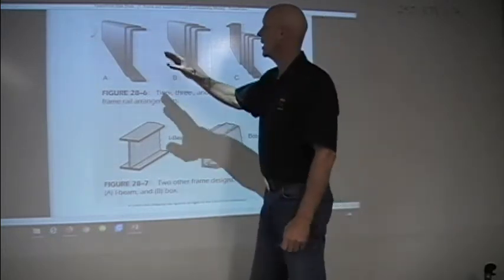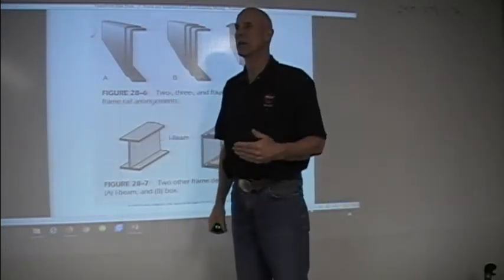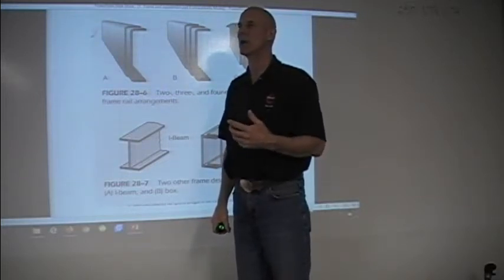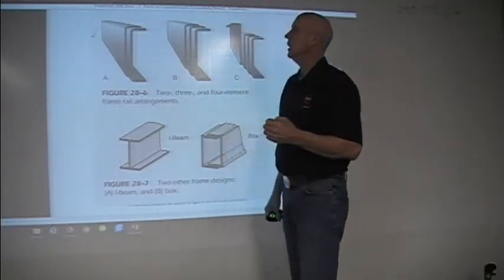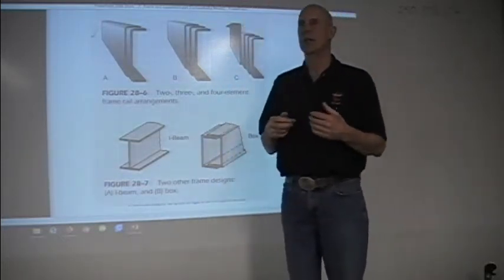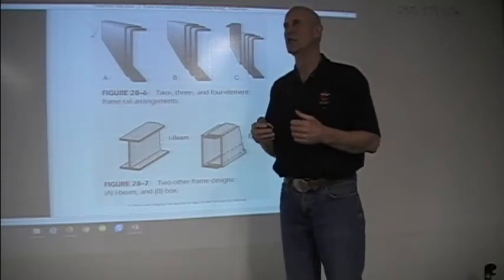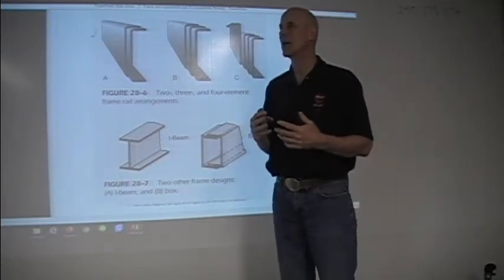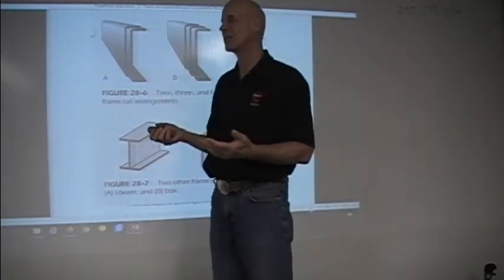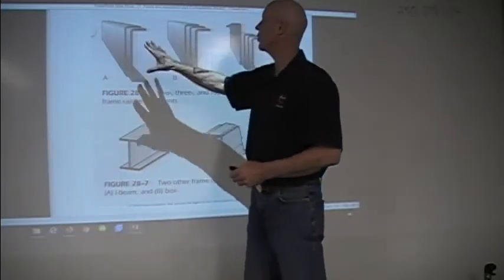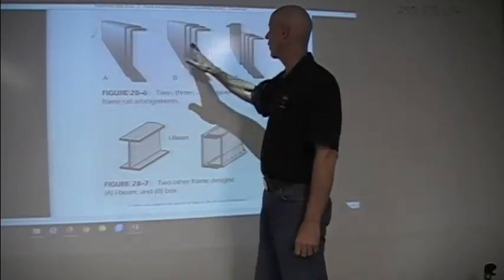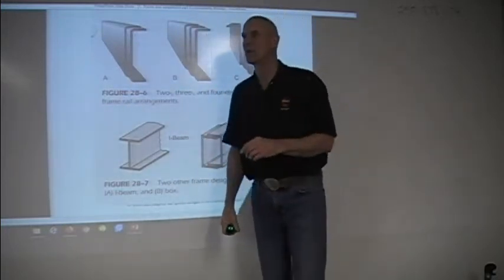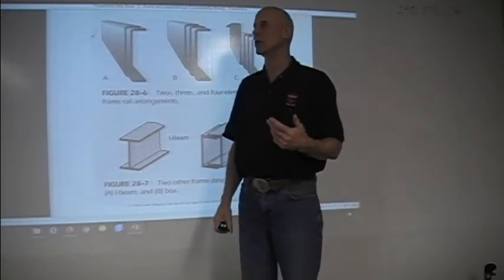So when they engineer and design a vehicle, every material has a certain amount of pressure which it can take. So for instance, aluminum will have 60,000 psi of pressure, where steel can take 110,000 psi of pressure. So they're going to design the frames for the application of the vehicle. Now, Mack came out with frames made of aluminum years and years ago.